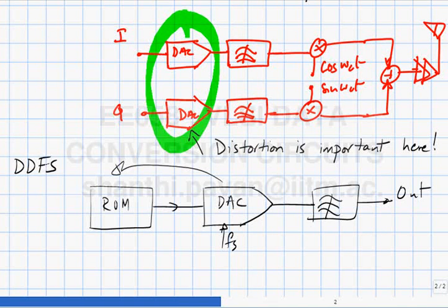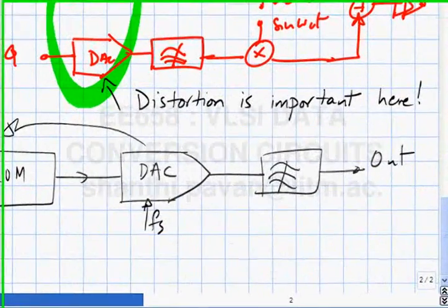You buy the DAC, you get some ROM and then glue the two together on a board and you're all set. So a lot of frequency synthesizers and function generators today, of the type you see in the lab, there's no more turning the knob. It can all be digitally controlled, and you can get very precise frequency and all this other stuff, because everything is done digitally, apart from the DAC, of course. So here also obviously distortion is a big concern, and so you want the DAC to be linear.